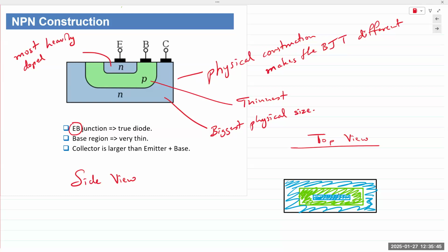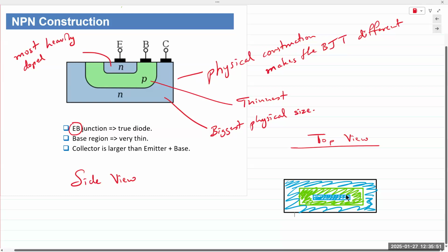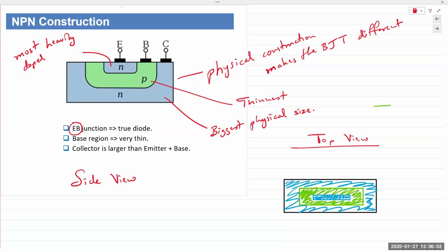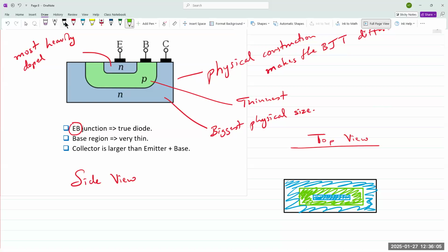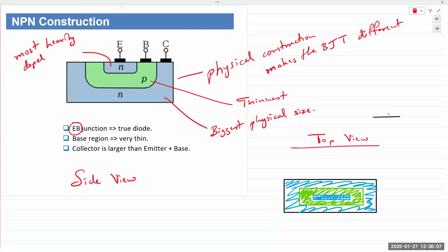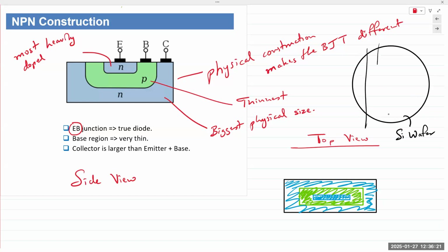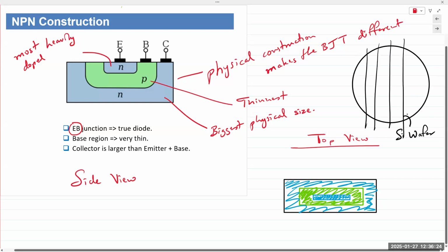Okay, we are working at the micro scale. And at the micro and nano scale, we cannot directly access and assemble our devices. So the way we work is with a process known as surface micromachining. We have our silicon wafers, flat, and looking at it from the top, this would be a silicon wafer. And it would be broken up into hundreds of devices.